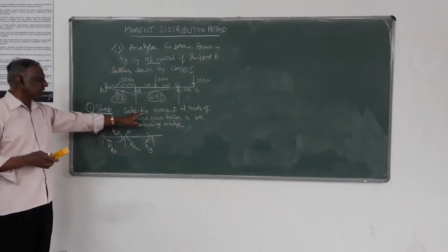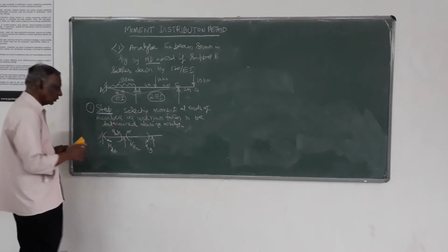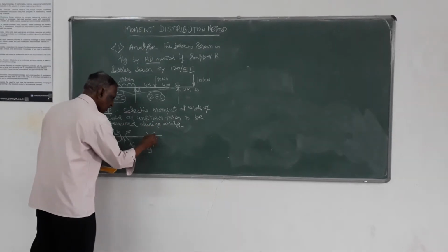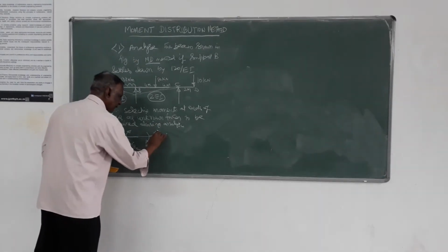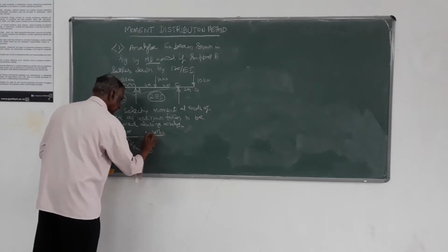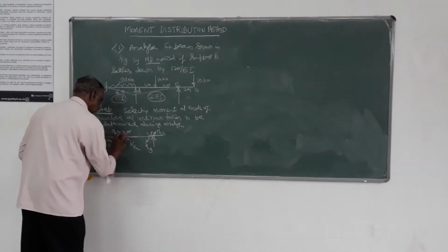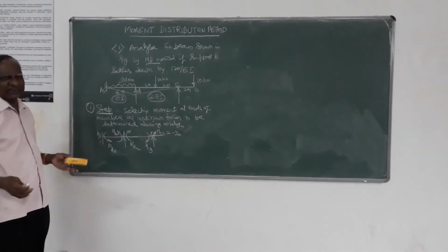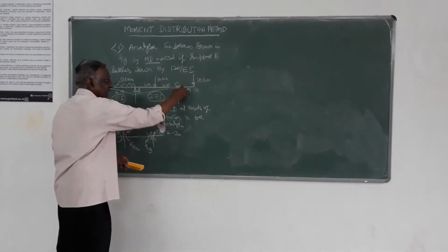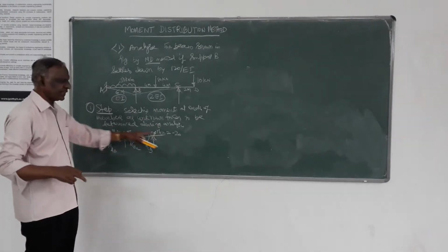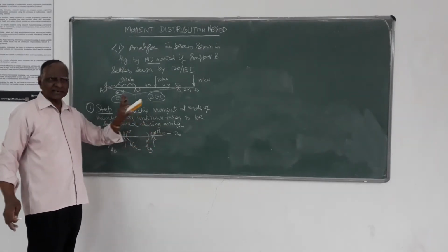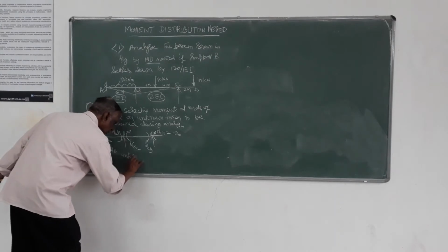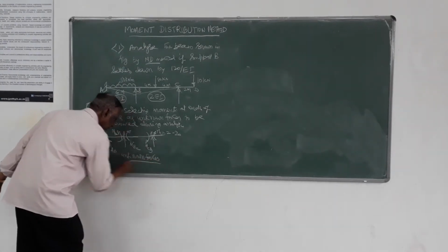So we have to determine the moments at the ends of members as the unknowns here also. If you treat this as a member, normally we don't treat this as a member, then this is the member and moment, that is MCD, MCB. So this moment is known. This MCD is nothing but minus 20 because the applied moment will be like this, resisting will be like this. Since we are taking all moments in the positive direction, this is already known. Only unknowns are 4. So these are unknown forces to be determined during analysis.